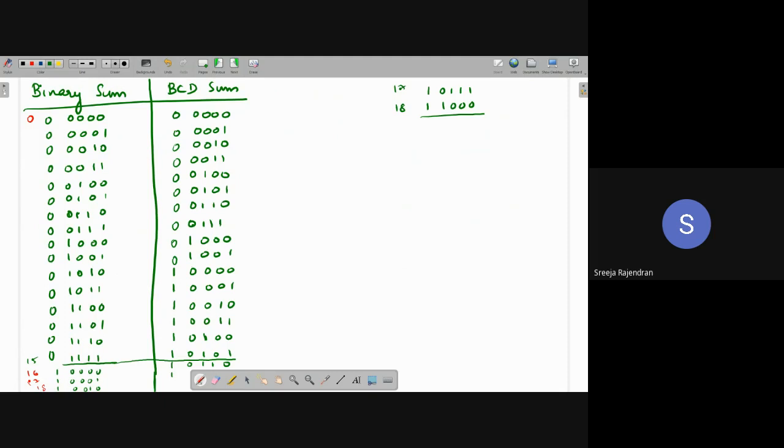Now, if I have a full adder, when I generate the sum bits, sum is generated, carry is generated. So I have to figure out how do I convert this problem using a full adder. How do I implement it? Okay, so let's look at that part. Now this additional MSB that I have, I call it as C star.